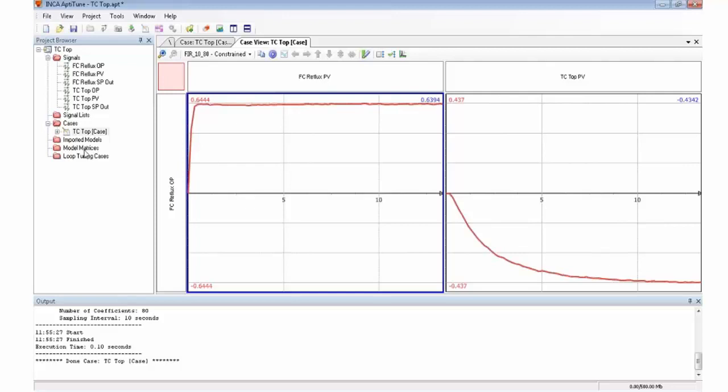I did one trial having one sampling time for both curves that I need. AptiTune is more flexible, and in fact if you would do this, and we're not trying to do two of these experiments in one webinar, I would recommend doing this with a faster, smaller sampling time.